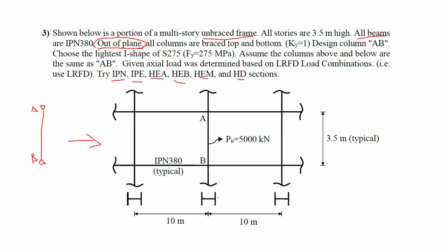Also, we are given the direction of the column, which is set, the wide flange. This is important to realize whether it's buckling about the x-axis or the y-axis. So this is an important piece of information for us. Usually the beams are placed in such a way that they buckle about their strong axis.